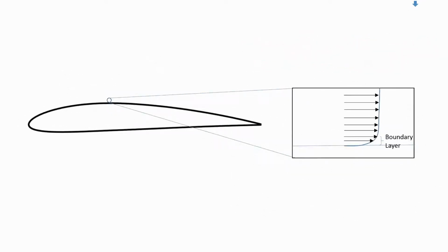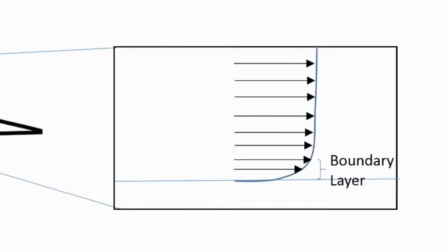Such a high Reynolds number means that the viscous forces are completely dominated by the inertia of the fluid. So much so that all the viscous effects are smushed down to a very thin region at the surface of the wing called the boundary layer. This means that nearly the entire region around an airfoil can be analyzed assuming incompressible, inviscid flow.